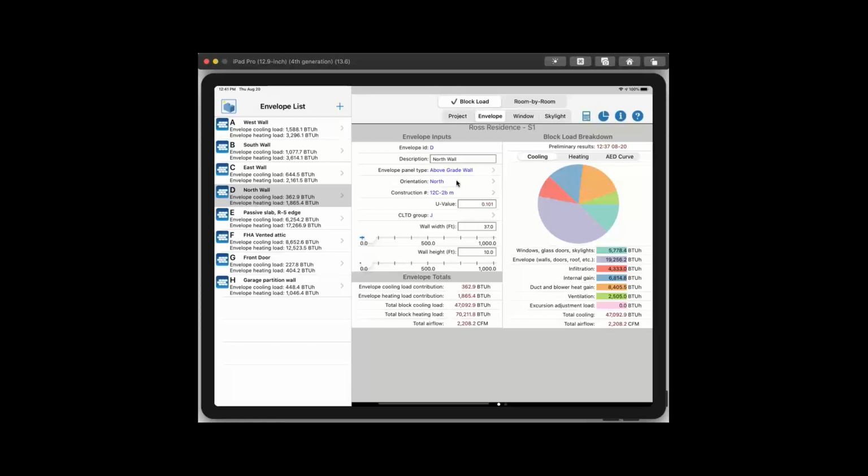So I'm double covering the windows, because they're in fact shaded north-facing windows in the construct that I was going to use. Exactly. That's what you would do. And I'll show you in the next section where you can assign the windows to the wall. If you assign windows to that north wall, those windows will also have very little fenestration load or solar load.